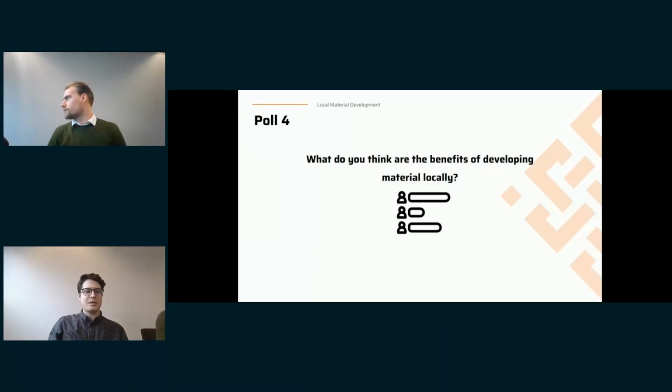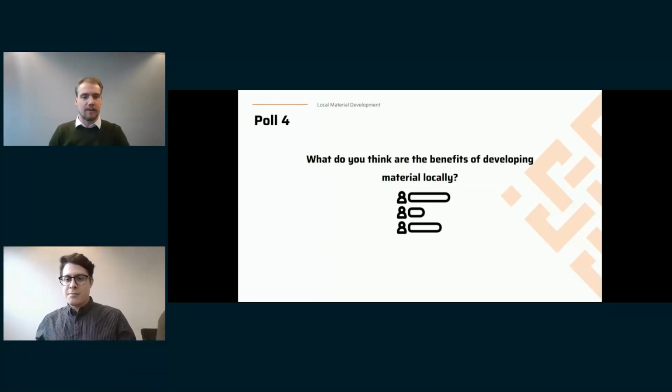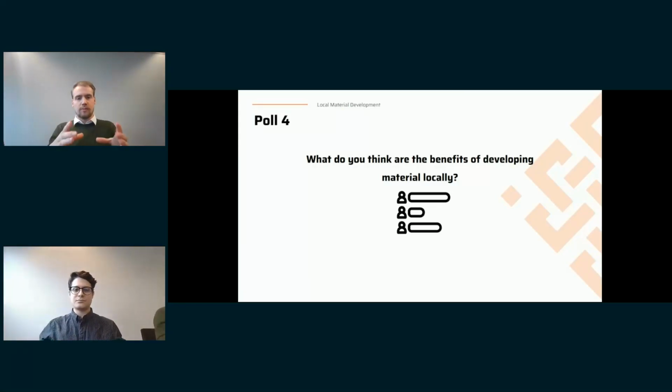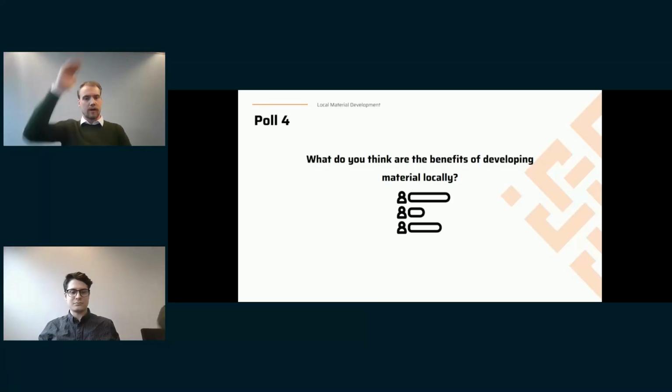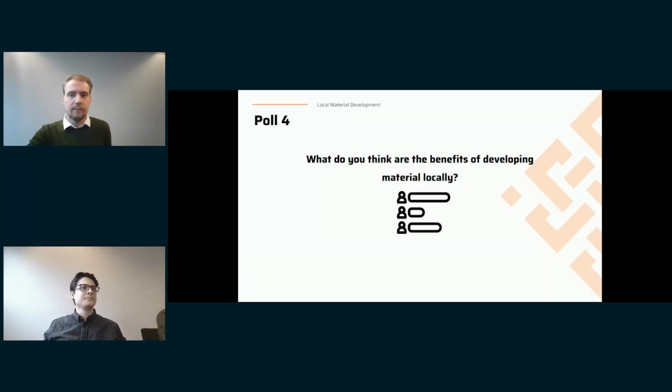Also, we are limited by the print reach of the robot. We can go with a very small object all the way from the ground up to the highest limit of our robot, which with the automatic height extension is around 4.2 meters. We can do that in one go without the bottom layer collapsing, which is one of the reasons we can print these elements so quickly, because we don't have to do it in segments. We can go full speed all the way to the top. I hope that answers your question. I hope I interpreted the question how you meant it.